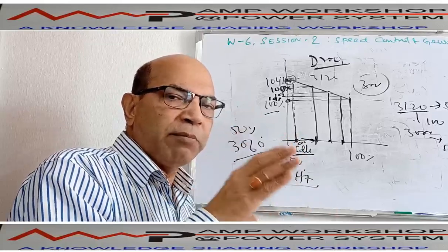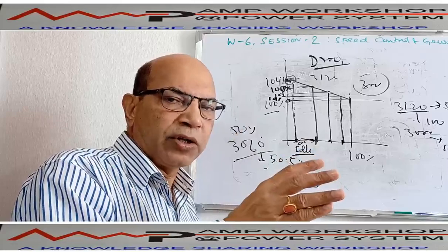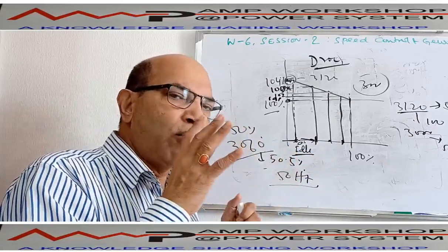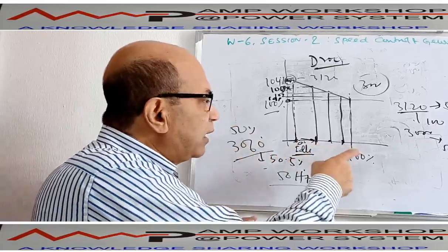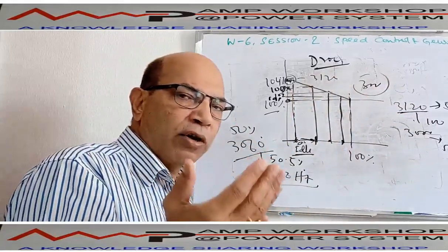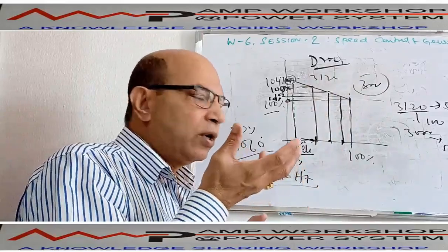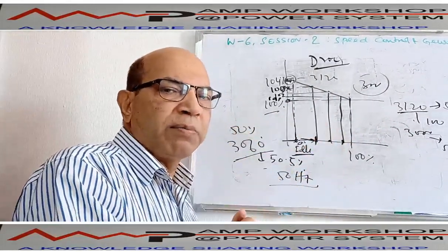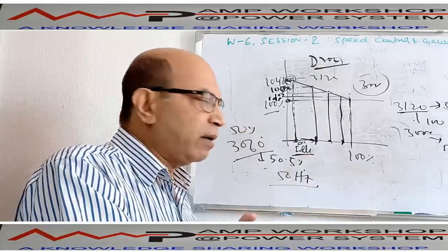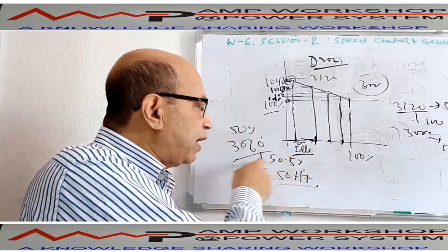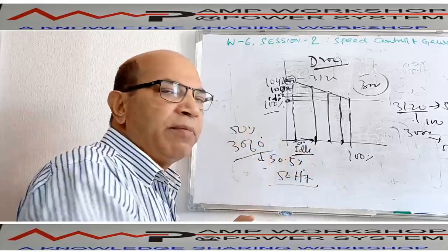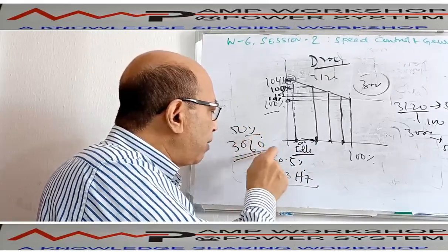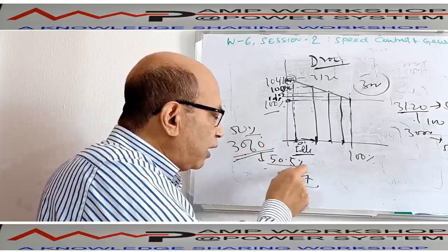The frequency of the output or the speed of the turbo generator set will be decided depending on the droop setting and the loading. So when the load is 100%, it will come back to 3000, meaning 50 hertz. But until the load is 100%, if you want to run at 50% loading of the machine, the natural frequency will not be 50 hertz. So by manual intervention, it is brought back to 50 hertz from the corresponding AVR governor speed. That means when you put 50% load, the governor will be running at 3060 speed, with the corresponding frequency.